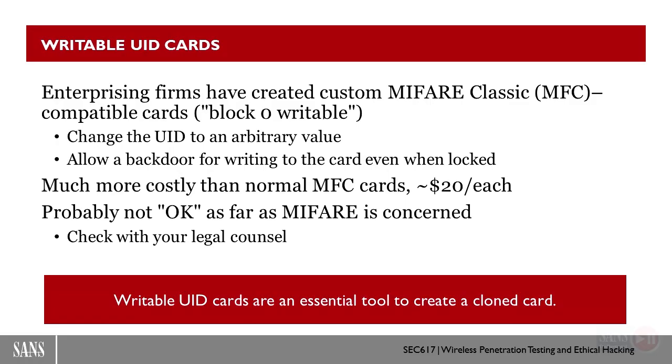In some cases, the cards will present themselves as being read-only to a standard reader, but with some additional commands sent to the card, it can, quote, unlock sector 0, block 0 to make it writable. So if queried by a reader without the magic commands, it will appear to be a regular card. Issue those magic commands, it is unlocked, and then we can write the UID to that block 0 sector 0.